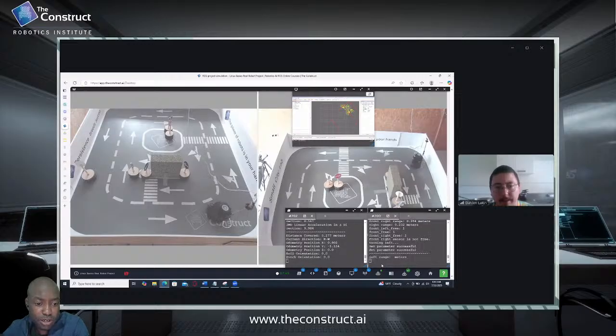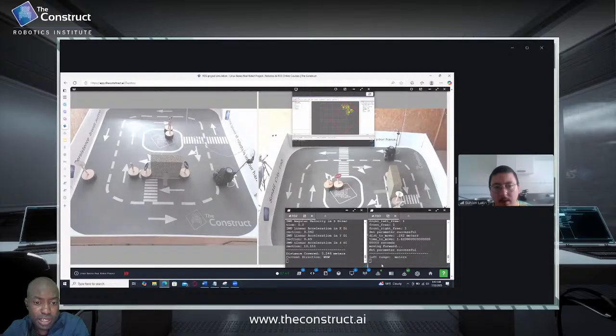Sometimes if your threshold is too small, for example 0.18, or let's just say 0.1 to make it very small, you'd realize that the robot will get too close to the obstacle, and when it tries to rotate, it cannot rotate to get out of its way because it touches the obstacle in the process of rotation. Correct. So it's very important to understand what the threshold distance is doing for you.